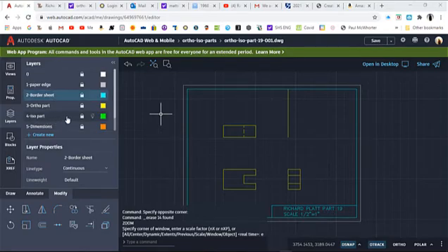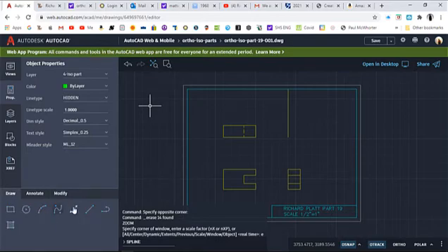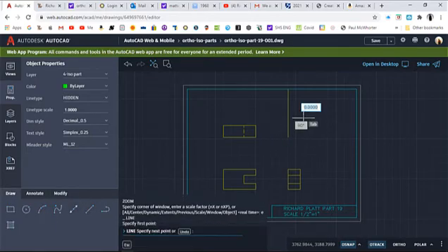So let's go ahead and select that layer, and let's unlock it. We'll move our mouse down, ensure the lock is gone, and that's the selected layer. Now, one thing we need to do is go to our Properties Manager and see how we're set to hidden. If we start drawing a line, let's go back over here to line, and start drawing a line. Let's go off here at this one point and just arbitrarily put a line in. See how it's got the dash for hidden line? We've got to reset that.